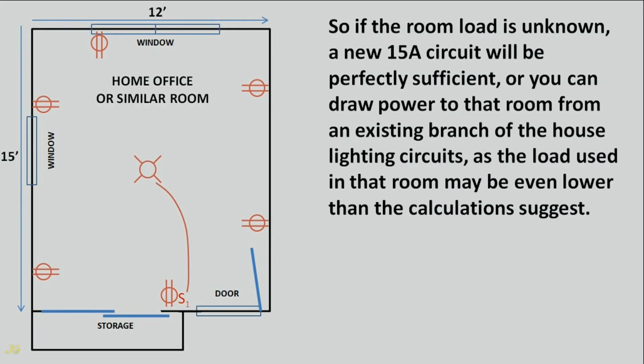So if the room load is unknown, a new 15 amp circuit will be perfectly sufficient, or you can draw power to that room from an existing branch of the house lighting circuits, as the load used in that room may be even lower than the calculations suggest.